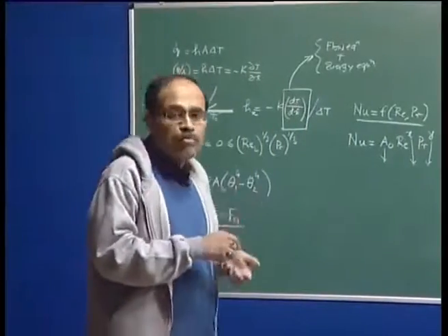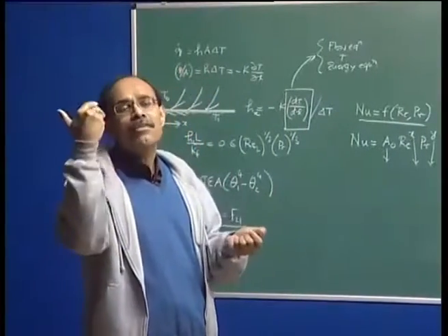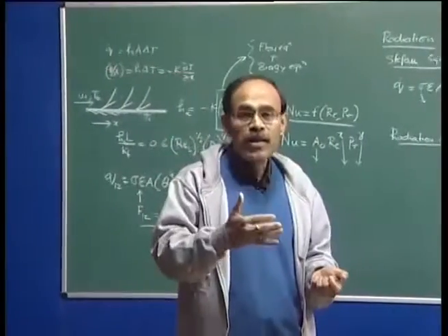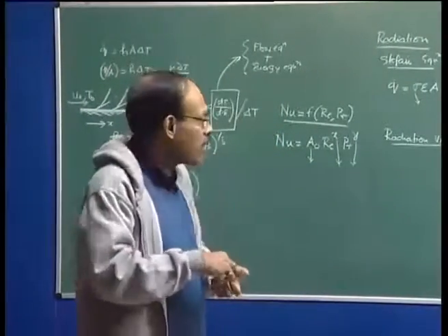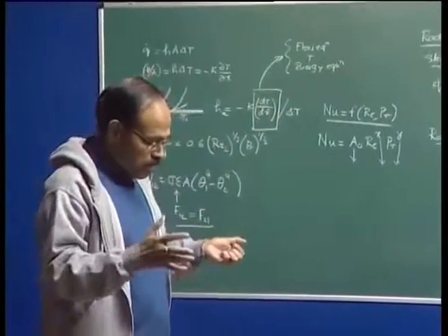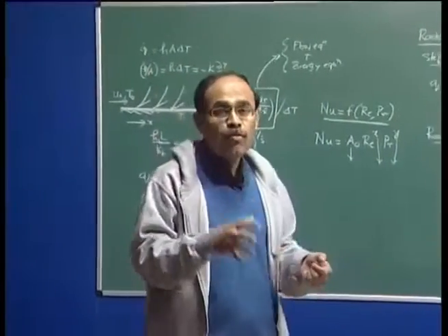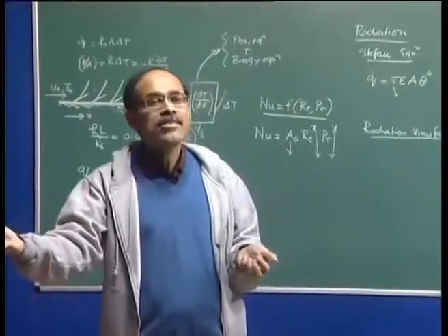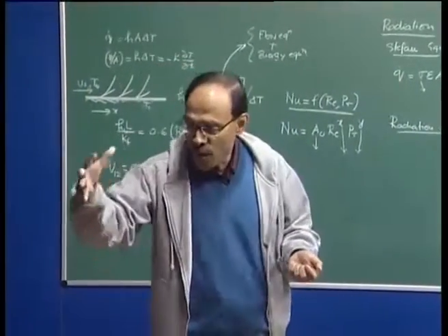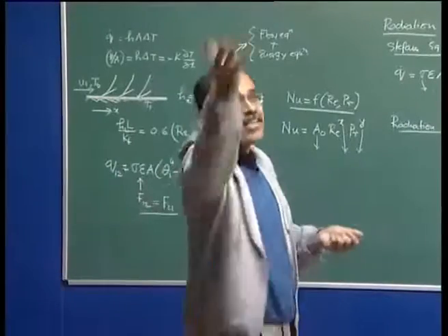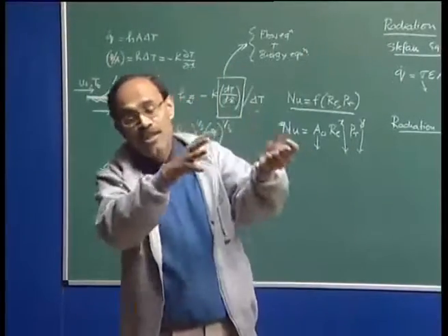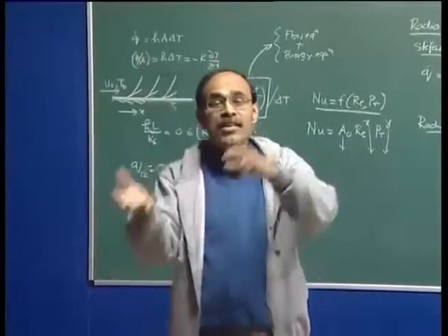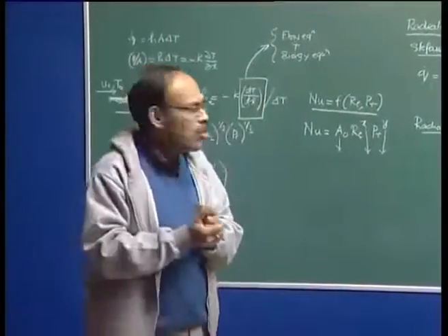You will be talking about mass transport in desulfurization, where you are concerned about transferring sulfur from metal to the slag. You would be talking about mass transport when you are doing tank degassing or vacuum degassing operation. How? Because you have dissolved gases in the melt, and now you want to drive those dissolved gases into the ambient atmosphere. So it is a transport of dissolved gases like nitrogen, hydrogen, etc. from the melt into the ambient. So we are talking about mass transport.